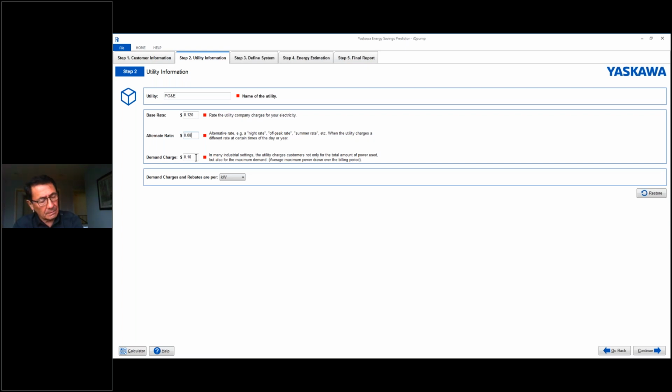In the case of the power grid in Guyana, I cite this application even though it's far away because it's a very good example of the fact that a soft start's not a very good peak power limiter. People think of soft starts as peak power limiters. They're not. A soft start doesn't control anything. It's a voltage ramping device, and it is intended primarily to reduce the output torque and shock to the driven system from the electric motor.